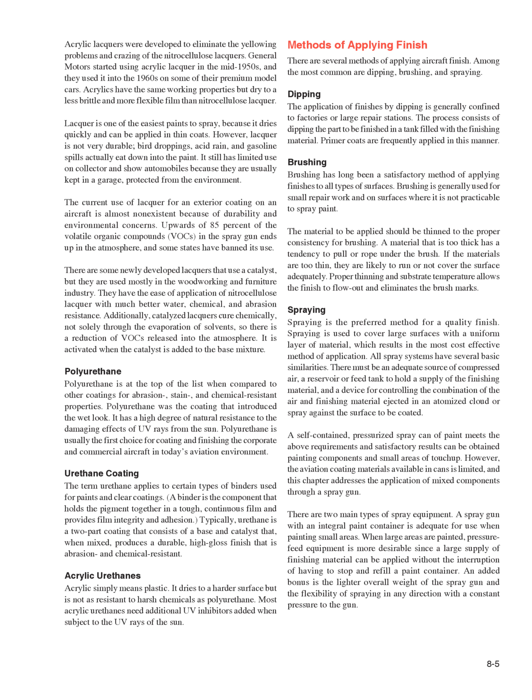Polyurethane is at the top of the list when compared to other coatings for abrasion, stain, and chemical resistant properties. Polyurethane was the coating that introduced the wet look. It has a high degree of natural resistance to the damaging effects of UV rays from the sun. Polyurethane is usually the first choice for coating and finishing the corporate and commercial aircraft in today's aviation environment.